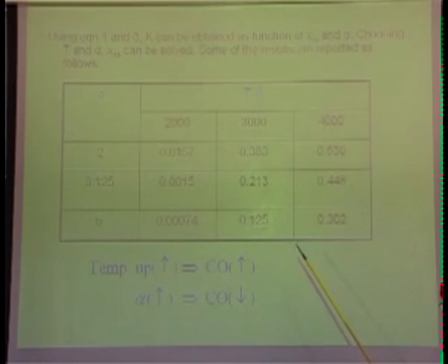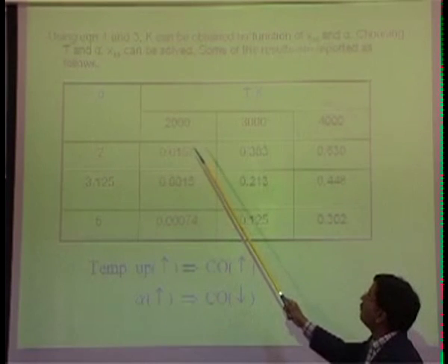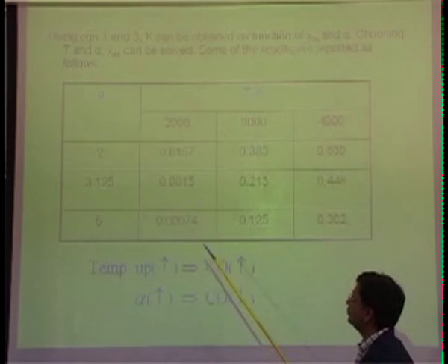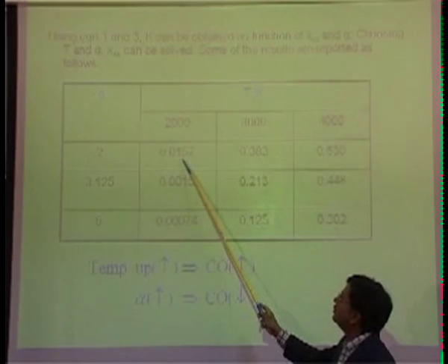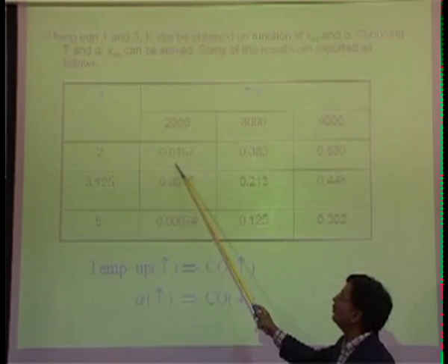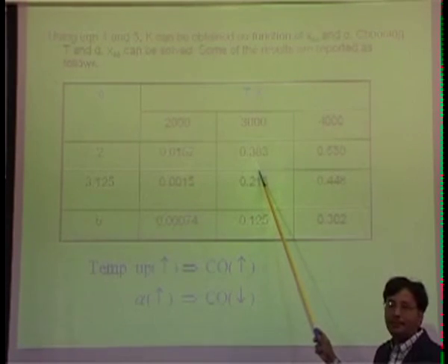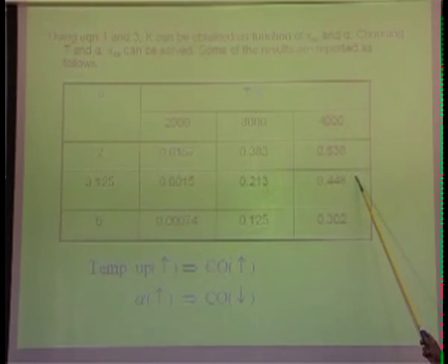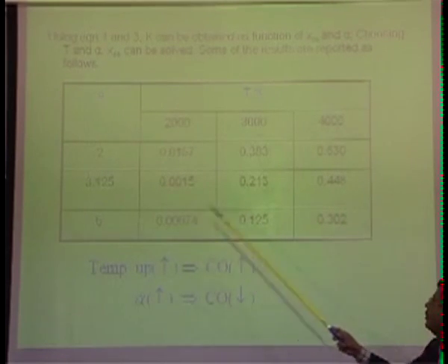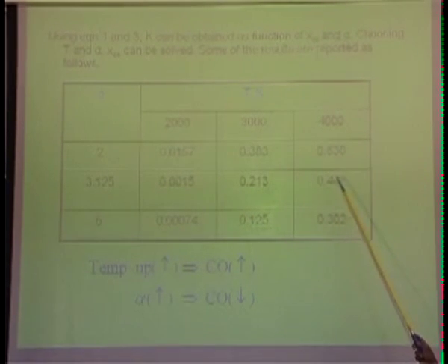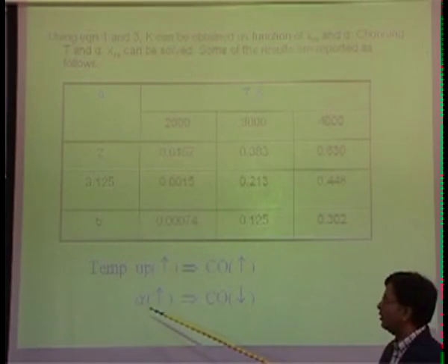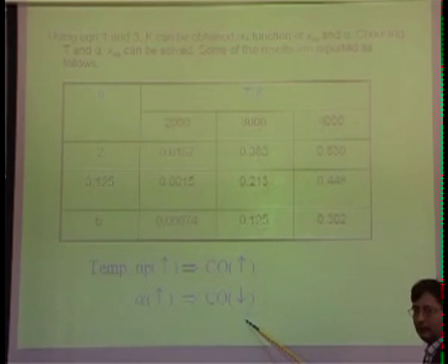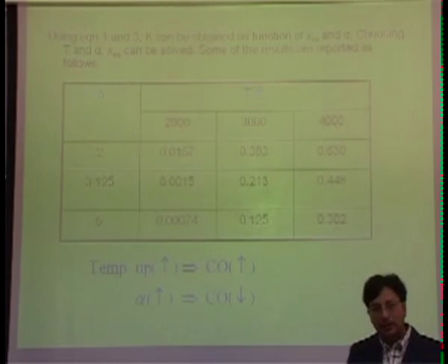Okay, but see, if from the same expression, I am increasing the temperature of combustion, so this mole fraction of CO went up. You can do this calculation yourself. I increase the temperature even more, and of course the situation is the same, I am forming more CO. So again, this is a summary here. The temperature is up, the CO is up. Alpha is up, CO is down. Alpha up means I am putting in more oxygen.